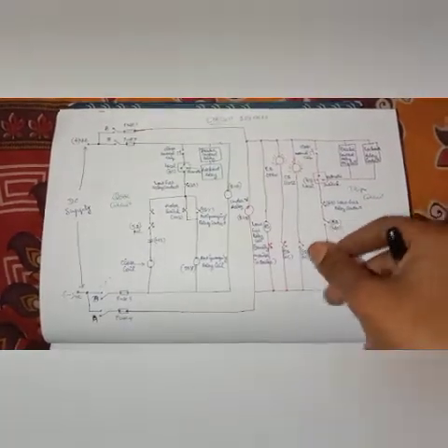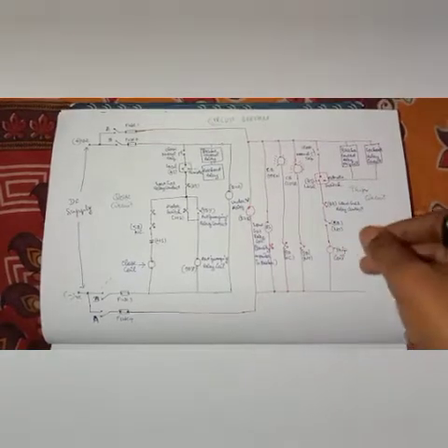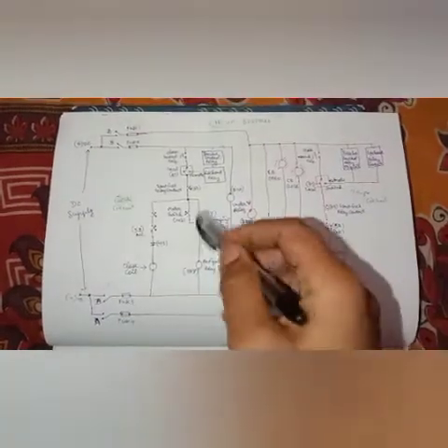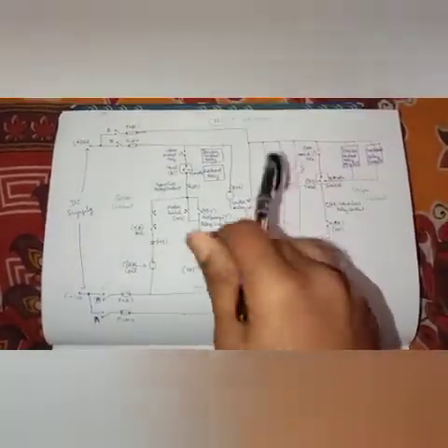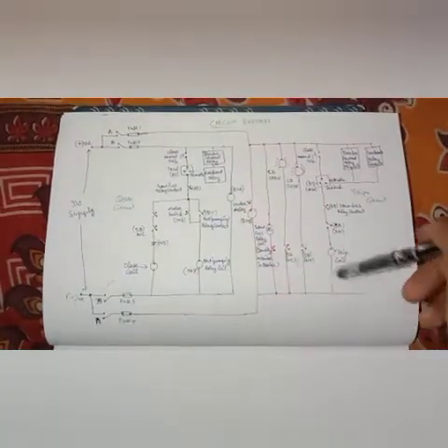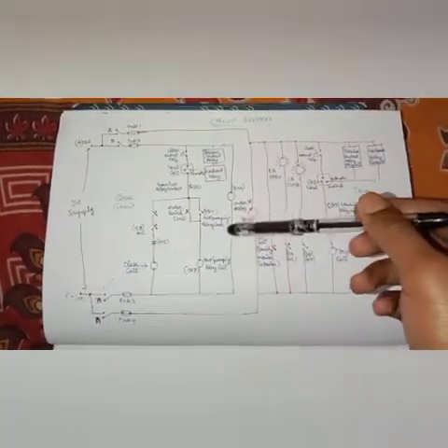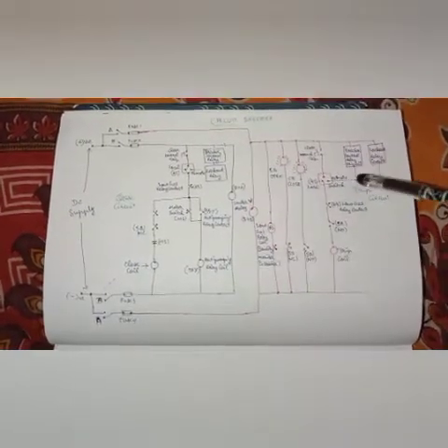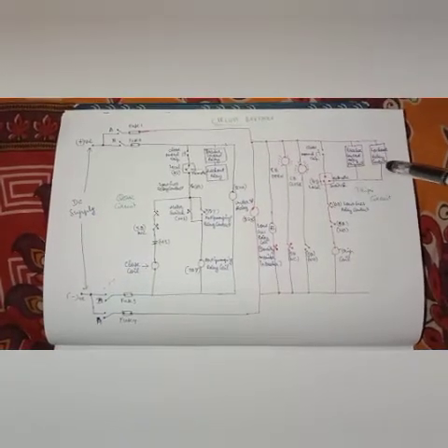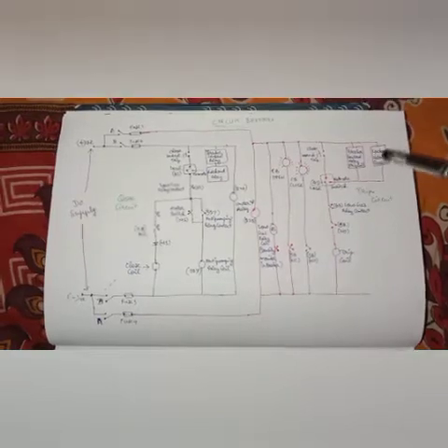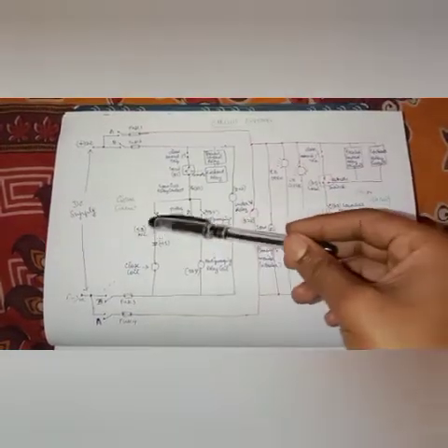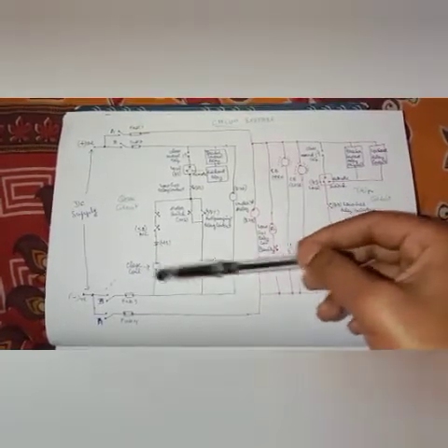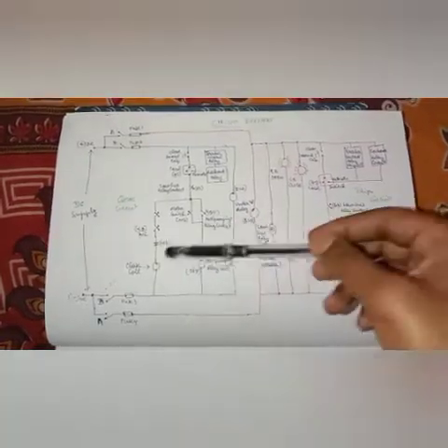So the diagram may vary according to your placement, or according to the variation in your circuit breakers, but the closing and tripping circuit will mostly follow these basic ideas only, and further it will be developed by additionally adding some auxiliary contacts or auxiliary relays, interlockings, and on the tripping side we will add extra trippings, additional trippings, inter-trippings like this. Likewise, in parallel we will add the trippings, and in series we will connect some of the interlocks in between closing and tripping circuits.